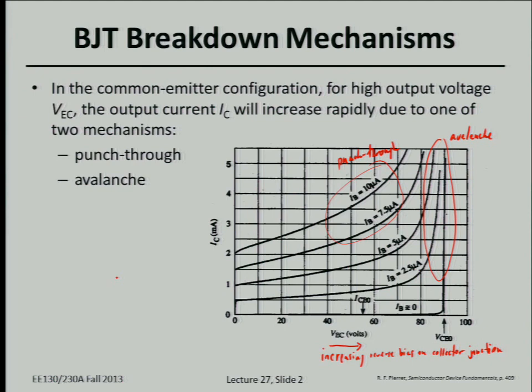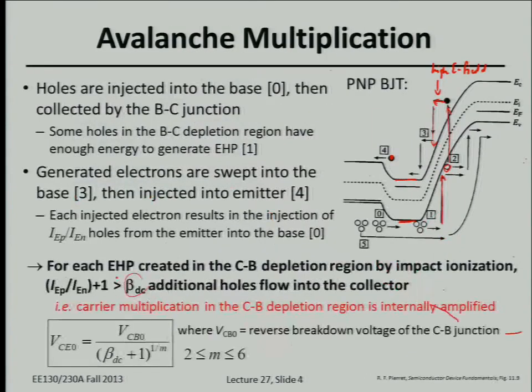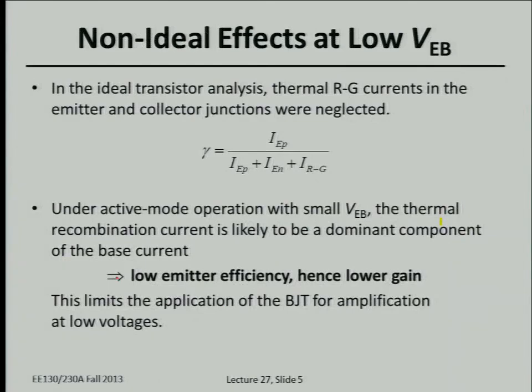applications. So for high voltage switching, you would design the base and the doping of the collector, especially the collector doping and the length of the collector region. That is quite different for the different applications. Yeah. So most of this voltage can be dropped across the collector region, the collector junction. Okay, so that's one non-ideal behavior.